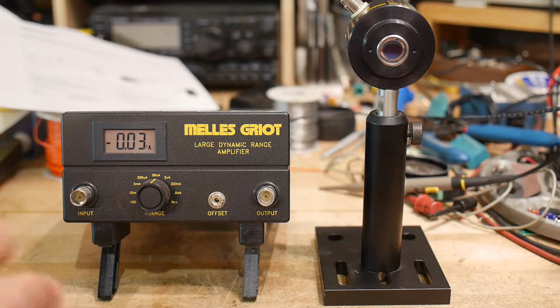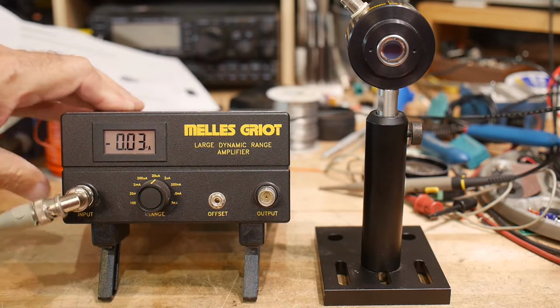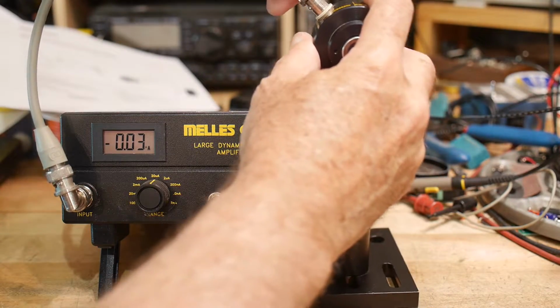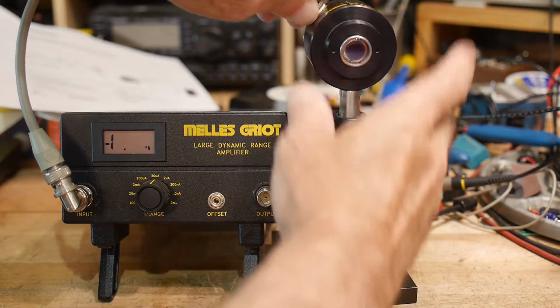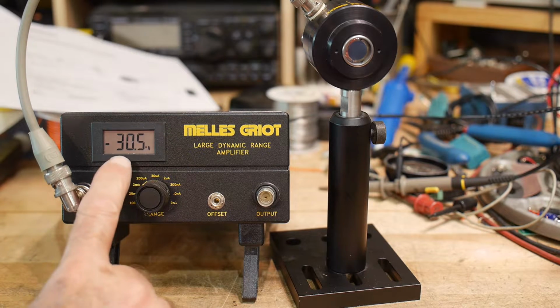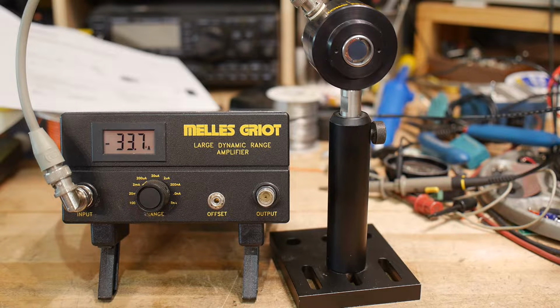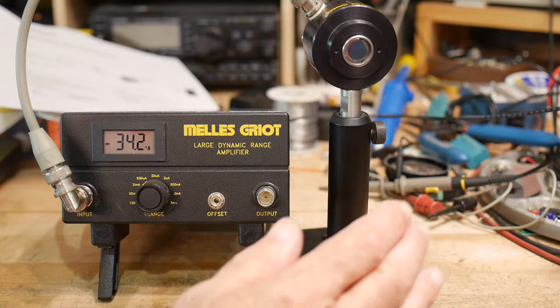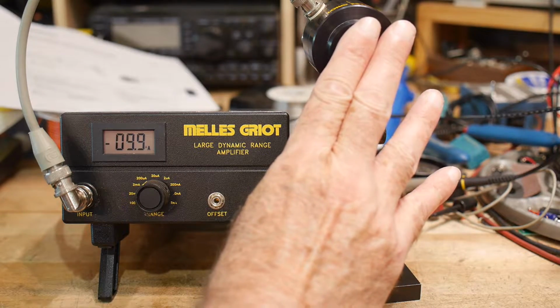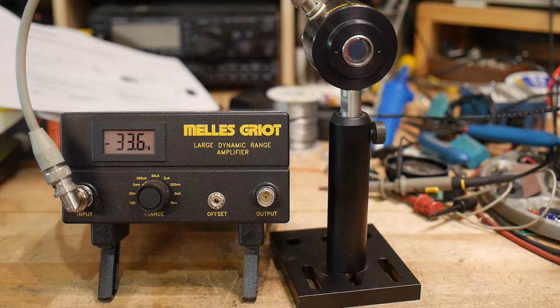And then you need to amplify those because it usually is a pretty small signal. So we have an input here to our amplifier, and we can hook that up to our photodiode, and we can set the range, and it says 30 microamps, about 30 to 33 microamps. If I cover up the photodiode, it goes down, and if I uncover it, light hits it and it goes up.